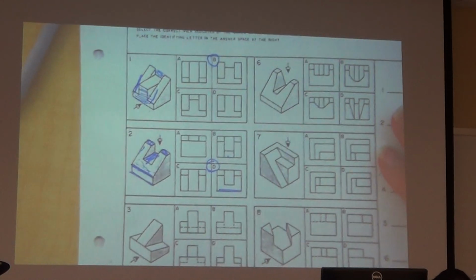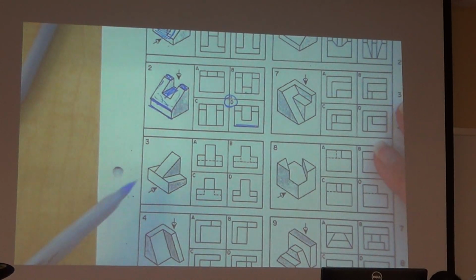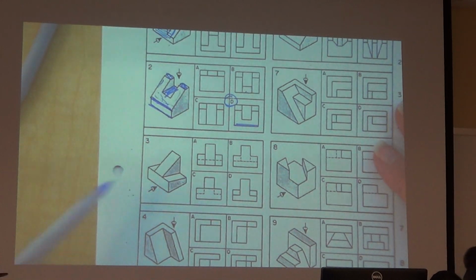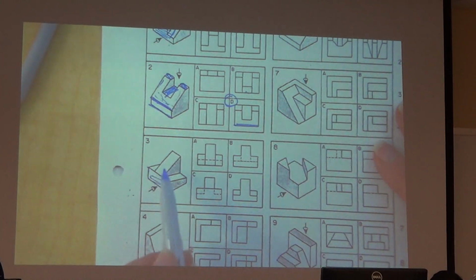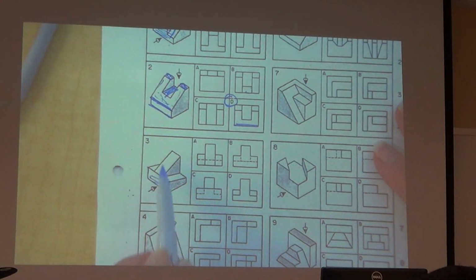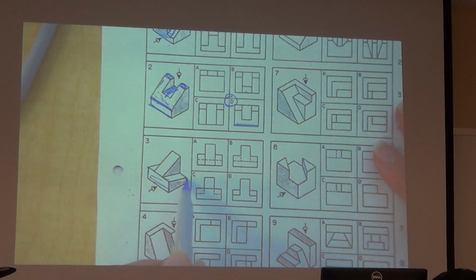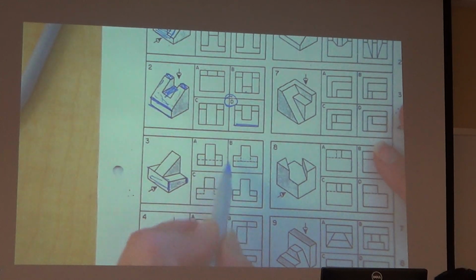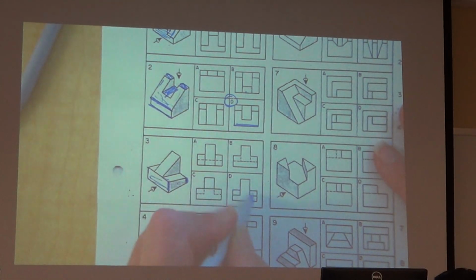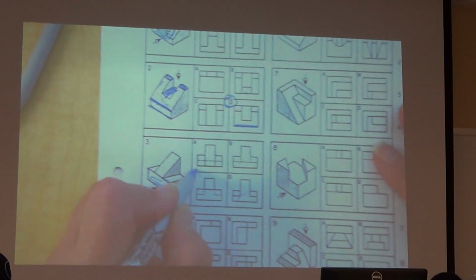Okay. Let's look at number 3. Arian, number 3. So again, it's an isometric view. I'm looking at it from the left side, or the front rather, sorry, the front. And I see a rectangle here. This, even though it's slanted, it looks vertical to me. But then notice that this slants down, right? So this height, does everybody agree that this height is smaller than this height right here? So there's this edge back there that I can't see. So I have to have this. This can't be, because it's got to be a hidden line if it's in the back. So which one is it? C. C.